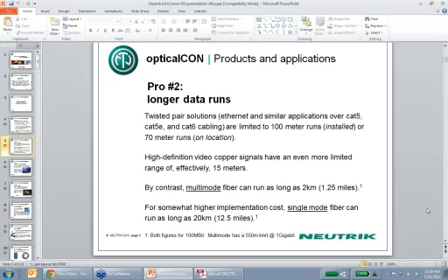And I do have to say, I'm the point of contact for Neutrik technical support questions in the U.S. And I do get these people who call in and say, hey, I'm having some problems with my system. And after a lot of questions, it turns out that they're running their copper cabling, their Cat5 or their Cat6 or their HDMI, just a little bit longer than they really should and than they technically should. And they get in these edge cases where they start to have these problems where there's distortions, there's dropouts, what appears to be dead pixel areas, and other kinds of problems. So, when you're working with the copper world and you're working with these high bandwidth applications, Cat applications, you've got this 100-meter limitation.